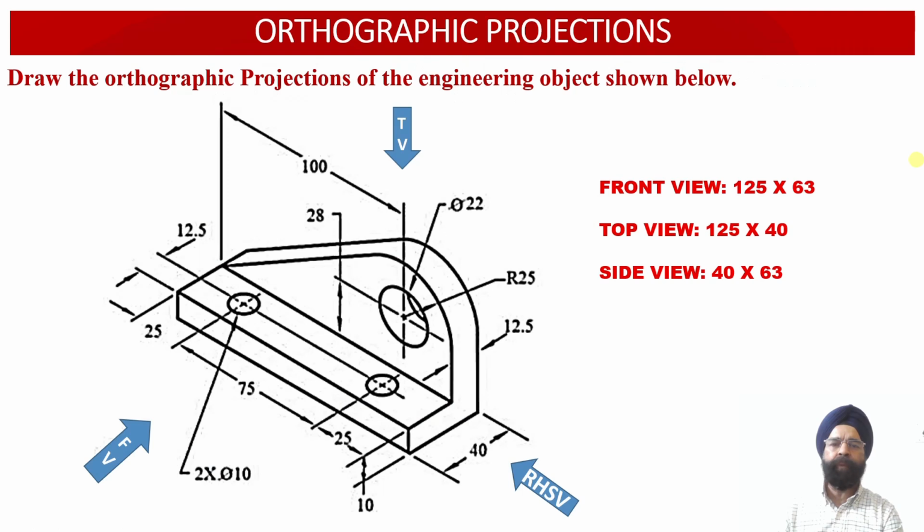Now here we have been provided with an isometric 3D projection of an engineering object whose front face, side view face and the top view face have been combined appropriately into the 3D isometric construction over here. With this information, we are required to evaluate the front view orthographic projection, the right hand side view orthographic projection and the top view orthographic projection of the solid over here.